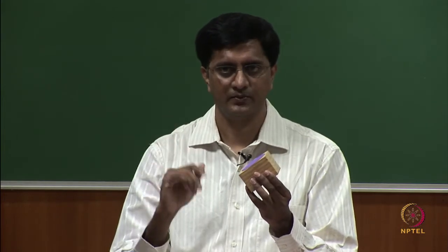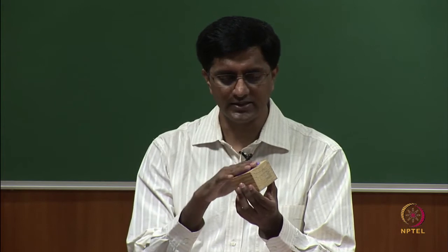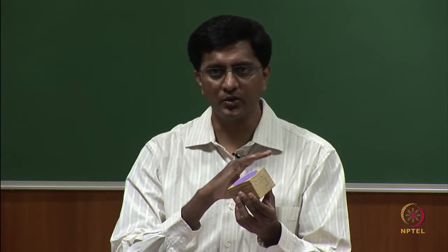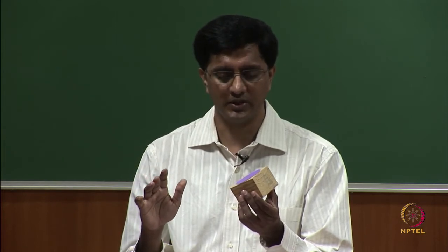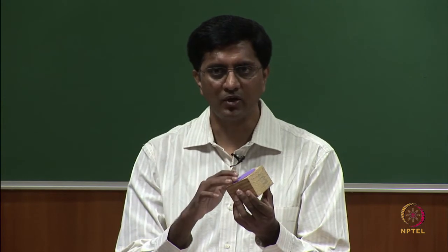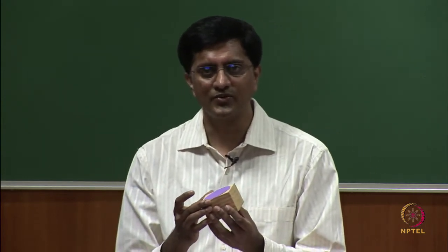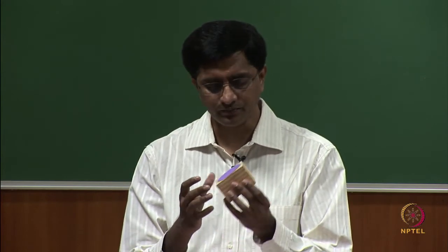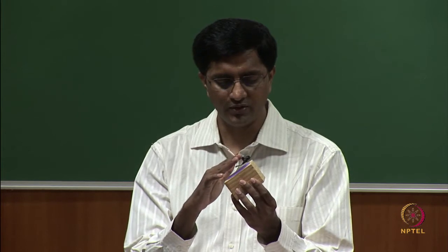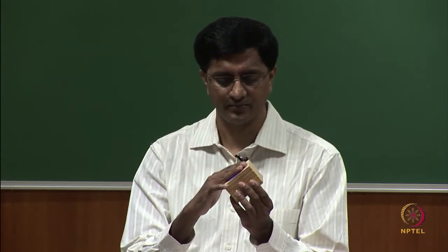So, this we call the inclined face because it is perpendicular to one of the planes. But let us say if I tilt it in a way that this surface is neither parallel nor perpendicular to any of the three principal planes, the horizontal, vertical and profile planes, then we call it an oblique face. The reason why I am emphasizing this is, now let us first start with an inclined face. So, now we said the one with the circular patch is the inclined face.